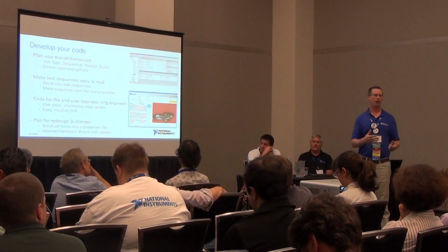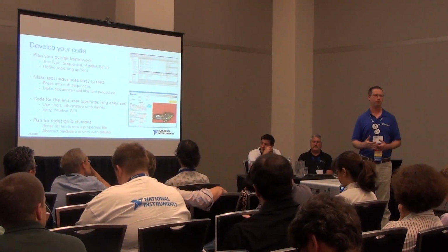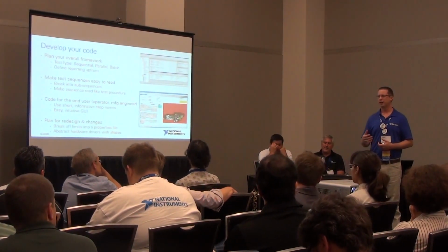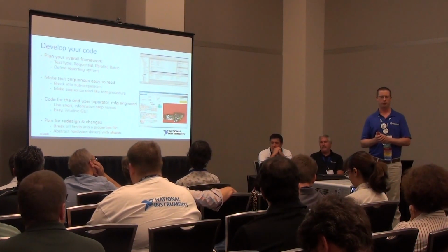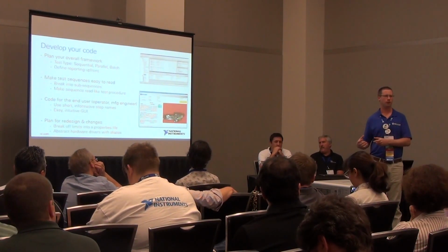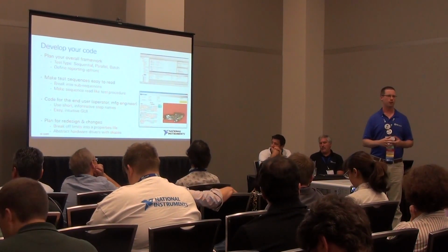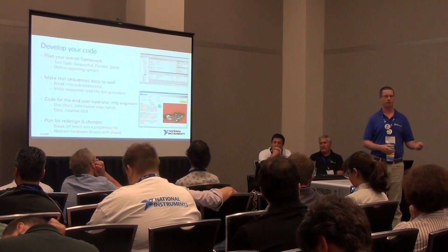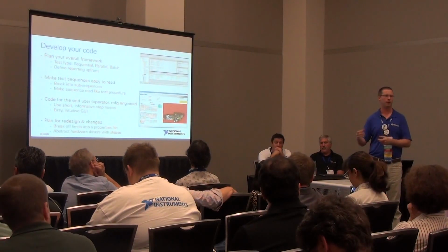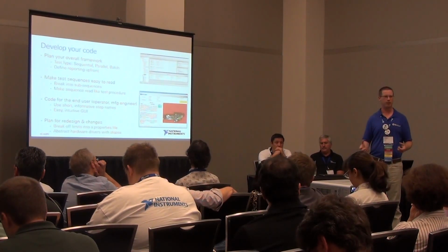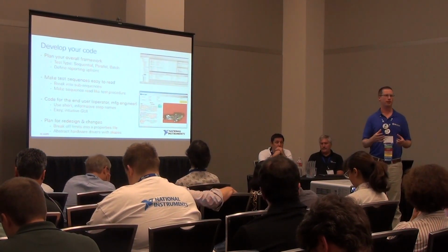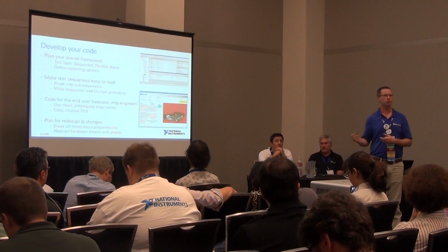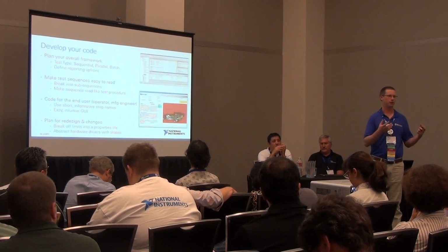And if possible, a big thing that I'm a big proponent of is hardware abstraction. By implementing hardware abstraction, you actually reduce the coupling between your low-level code and your test sequence code. So you can have test developers writing test sequences while hardware engineers are developing the hardware in parallel. That'll speed up your test development time, and it also makes it a little bit easier if you have an instrument go obsolete or fail. You can swap something else in without affecting your high-level test code.